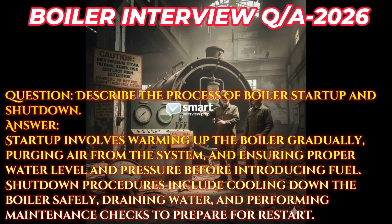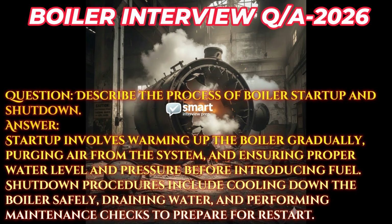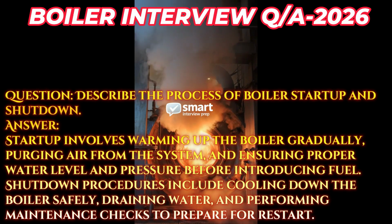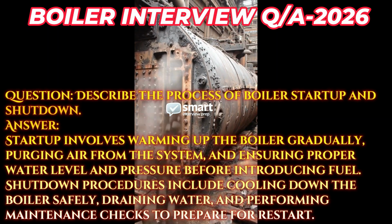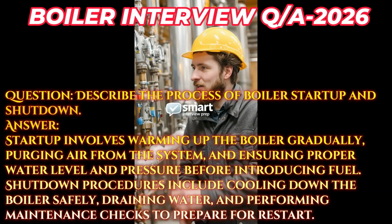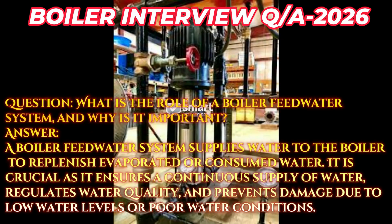Question: describe the process of boiler startup and shutdown. Answer: startup involves warming up the boiler gradually, purging air from the system, and ensuring proper water level and pressure before introducing fuel. Shutdown procedures include cooling down the boiler safely, draining water, and performing maintenance checks to prepare for restart.